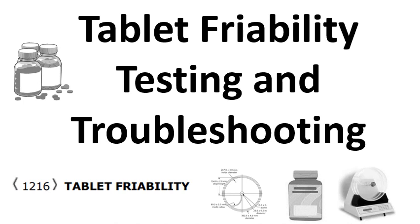As an in-process test, friability is an important test for tablet formulations, and friability is performed initially and during the compression run. The test is important because if the friability of the formulation is not proper, then the downstream processing like handling the core tablet, packaging and film coating becomes difficult,